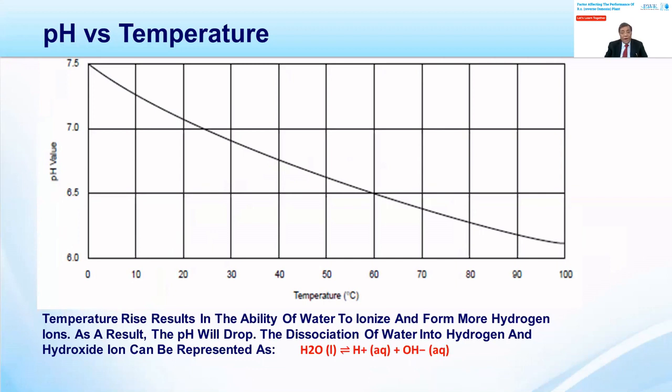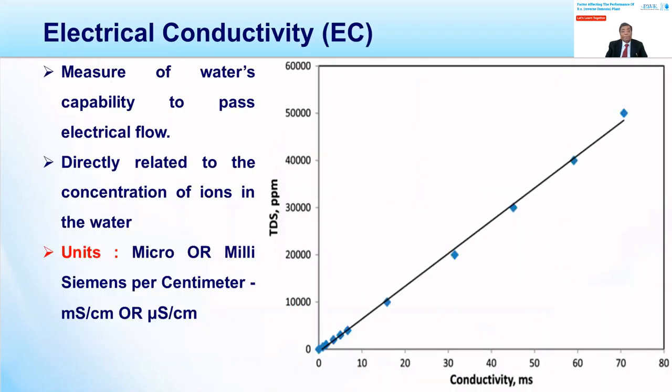You can see from this graph, because we have the bicarbonates, HCO3, and they dissociate into carbon dioxide and hydroxyl ion. They increase the alkalinity of the water, and these are the reasons. That's why, by decomposition of various ions in the aqueous solution, you can see the equilibrium shifts, and we have different pH at different temperatures for water of the same TDS.